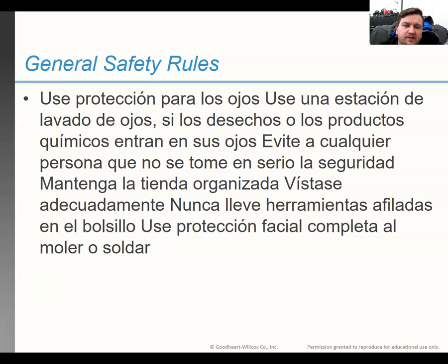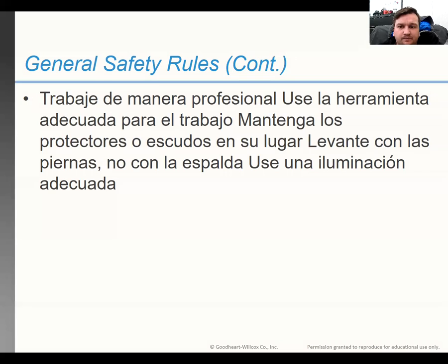And wear full face protection when grinding or welding. So when you're grinding or welding, obviously you want to wear full face protection. Safety glasses aren't enough. Welding is a very bright light. We need a special shaded lens to help protect your eyes from that.